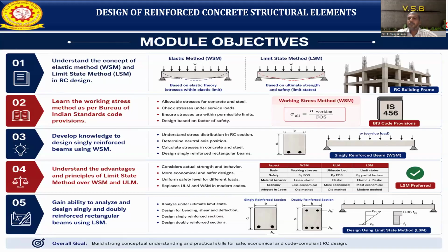Okay, now you need to learn the various types of working stresses, what the allowable stresses are for the concrete as well as the steel. We need to check each and every concrete structural member, and check the various stresses acting under the service load.